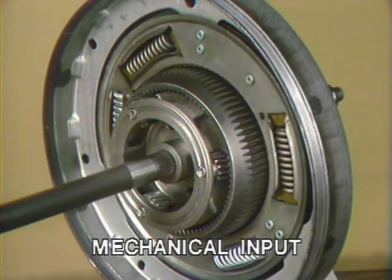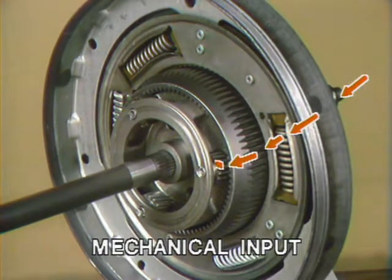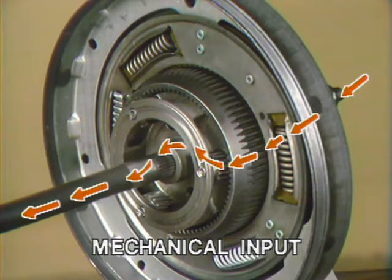Thus, the power flow for mechanical input is always from the engine to the converter cover, to the damper, to the splitter ring gear, to the planet pinions, to the pinion carrier, and through the intermediate shaft to the main gear train.